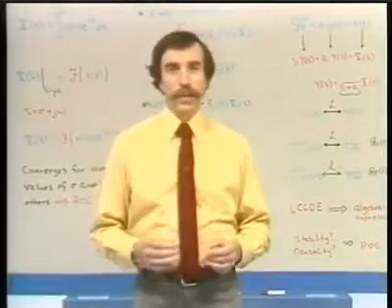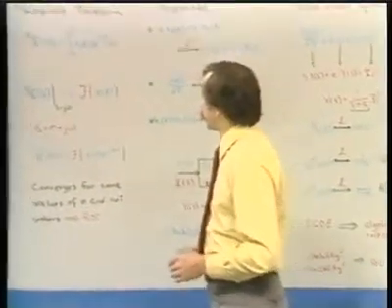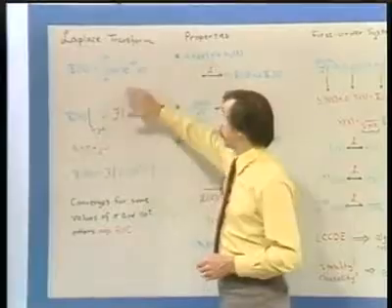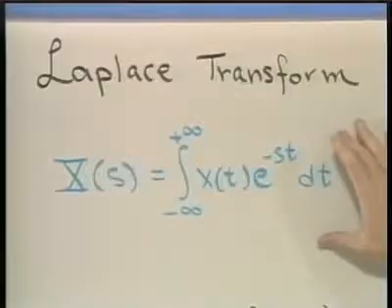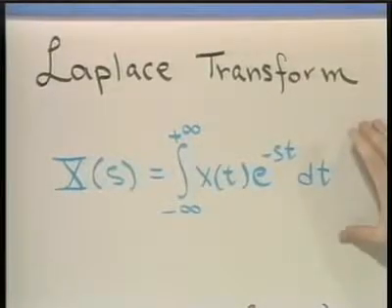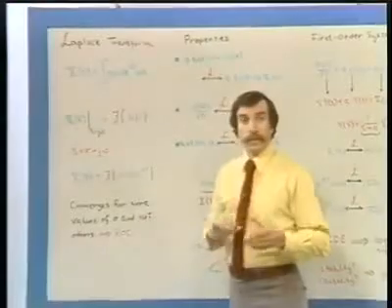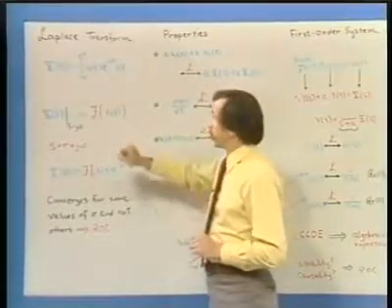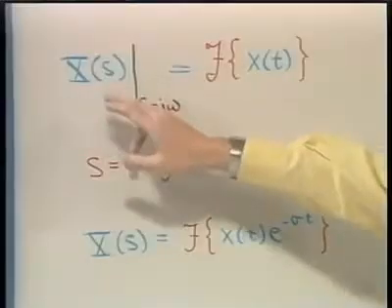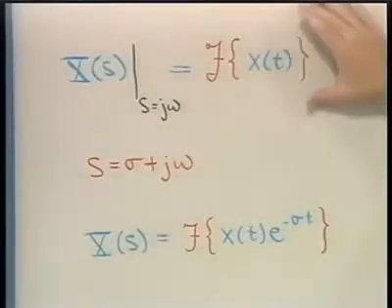Last time we introduced the Laplace transform as a generalization of the Fourier transform. And just as a reminder, the Laplace transform expression as we developed it is this integral, very much similar to the Fourier transform integral, except with a more general complex variable. And in fact, we developed and talked about the relationship between the Laplace transform and the Fourier transform. In particular, the Laplace transform with the Laplace transform variable s, purely imaginary, in fact reduces to the Fourier transform.